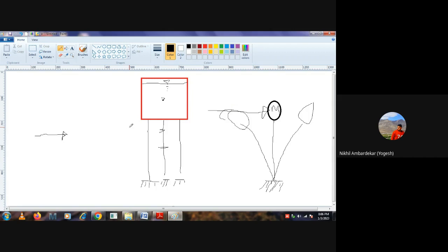We have placed this entire mass on top of a column, where the force will come and it will deflect. And based on that, as you also said, it will act at the top, at the base, at every junction. Definitely yes, it will be distributed based on the height. Clear? Yes. This concept is the lumped mass system. So we are just trying to simplify this, from a complex system to a single line diagram. So now it is very easy, correct?